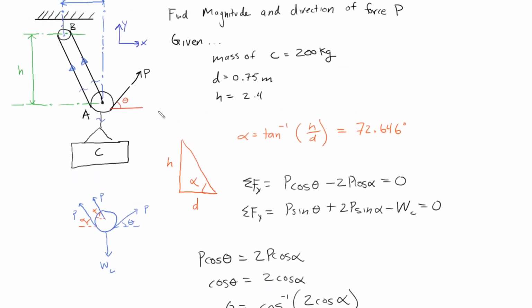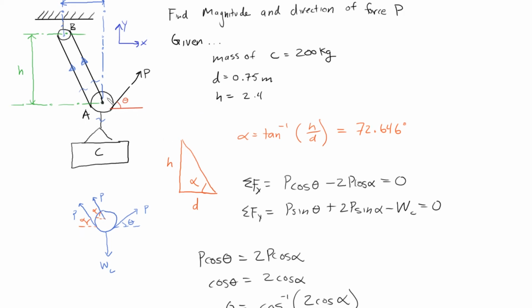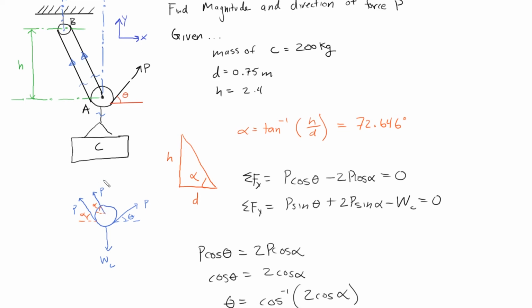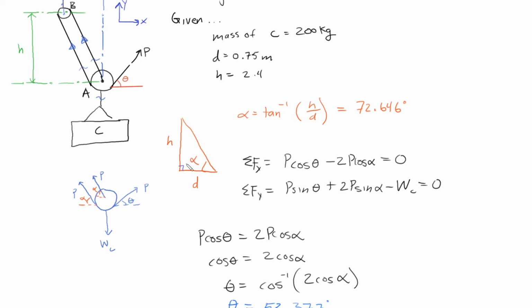And let me do a quick review of how we solved this problem. So we looked at a free body diagram of this pulley A, and figured out the ideas of tension, and we cut the tension ropes, and then we applied the idea of internal or reaction forces. And we recognized that these two tension cables are parallel, so we could find the angle by using this right triangle, given the dimensions of the problem.